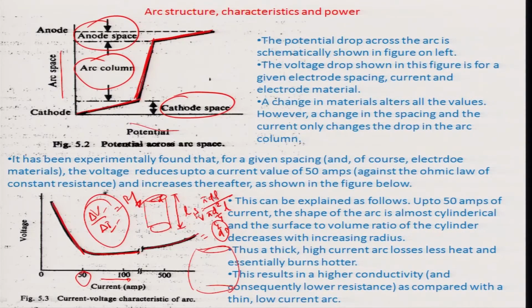And one of the reasons is that basically you have shields of opposite ions across the electrodes in question, which has to be penetrated, and so there is an energy loss if the electron comes out of the cathode or goes into the anode because of the surrounding charges. Whereas in the arc column, it is more or less like a resistive component, so there is not much which can be done about this thing actually.